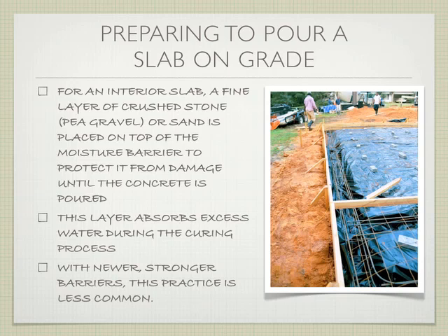We're using that as our moisture barrier, and we're leaving it alone. A little bit thicker, self-healing type material, okay? But this is another example. So similar thing we're talking about here. We have a simple edge form that runs here. We've got our stakes. Notice there's a vertical stake, but there's also a diagonal stake, so that this doesn't bow out when you put the concrete in.